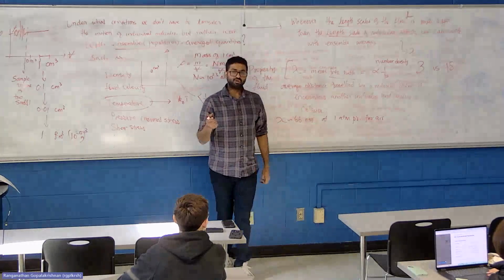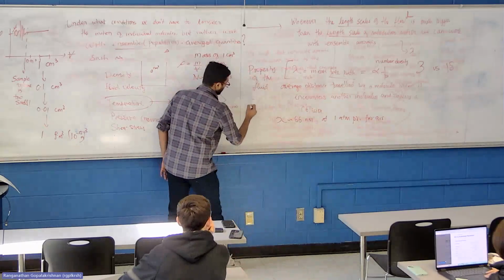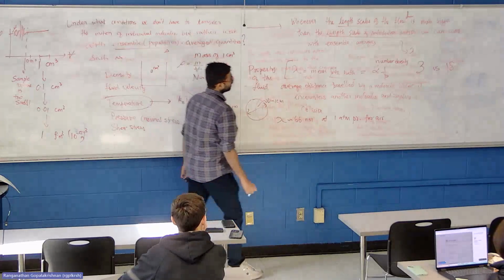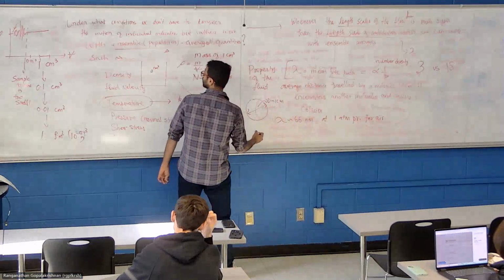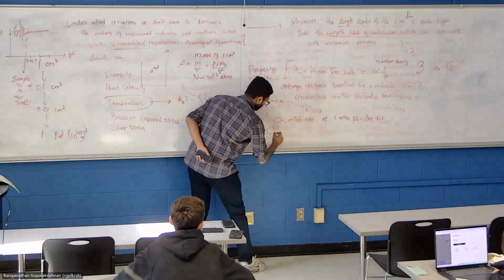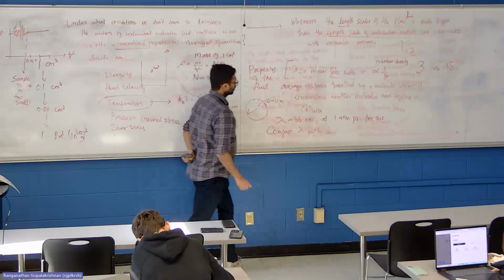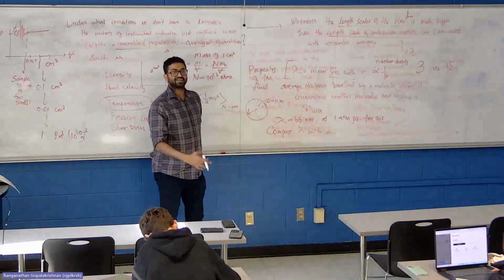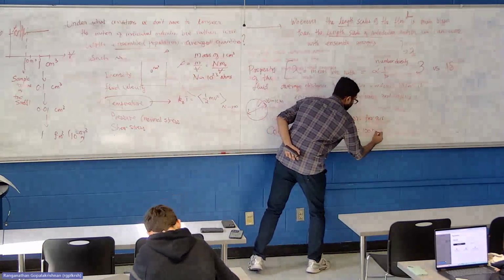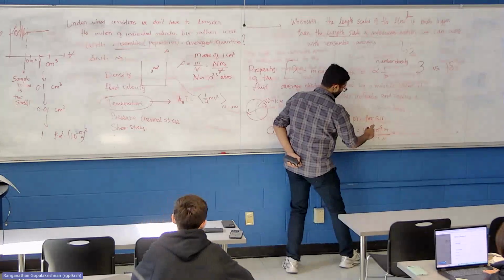Okay, so think of you are designing a pipe whose diameter is like a foot or even a centimeter. If you are interested in a pipe flow or a tube flow where the diameter is, we'll keep it simple, 1 centimeter, we just compare lambda with L. Just when I'm about to say something important, I run out of space. So we have 66 nanometers, which I'll simplify as 100 nanometers because I hate math. Lambda divided by L is 100 times 10^-9 meters divided by 10^-2 meters, which makes this 10^-5.